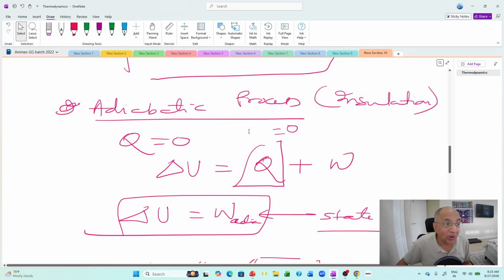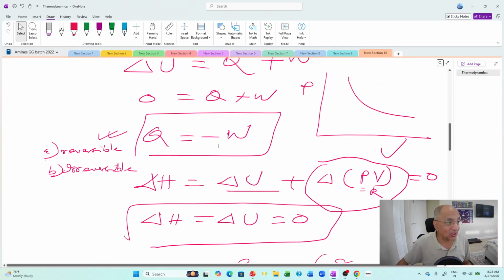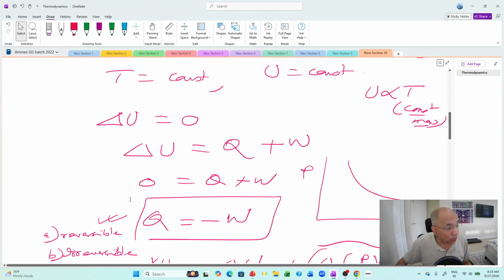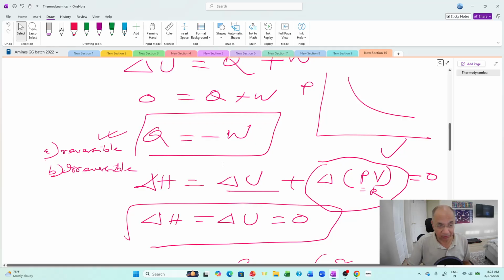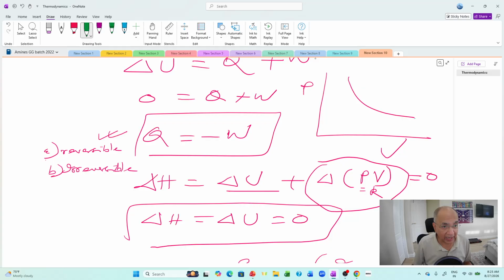Now compared to adiabatic process. So isothermal has two possibilities. One is reversible, the curve, and the irreversible, that goes under the final external pressure. The final that you are putting, 1 kg in place of 20 kg. That will work. So this is much less work in expansion, but more in compression, that we know. So that is irreversible. Reversible traces the same path.